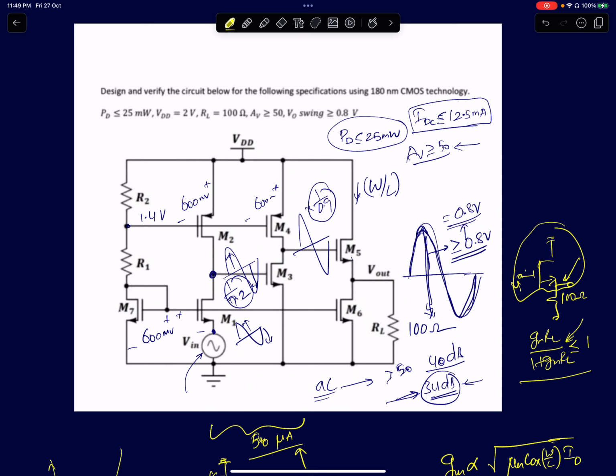In the assignments I designed for my students when I was teaching, I would not give the problems this way. It will be slightly different, but this is probably a good question. In one question, they are testing your understanding of all three amplifiers: common gate, common drain, and common source. So I gave you an idea how to split the gains. This is what you typically do when designing multi-stage amplifiers.